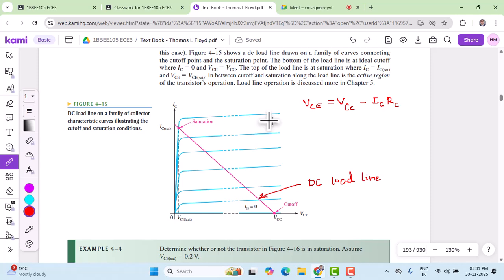This is the reason provided here for which one exceeds first. The power dissipation is going to be a very small value, so VC max is the one which highly depends on the VCC. Therefore, it exceeds first compared to the power dissipation value. Okay, so that's about the power dissipation.